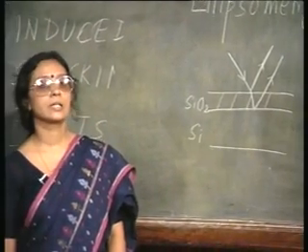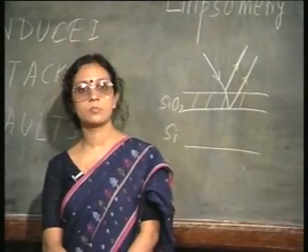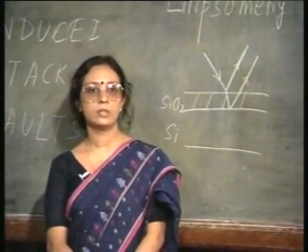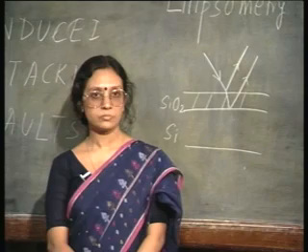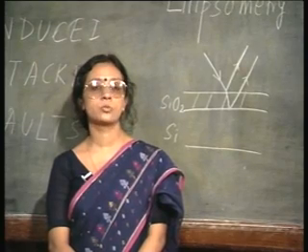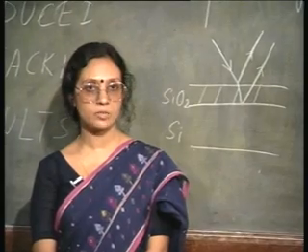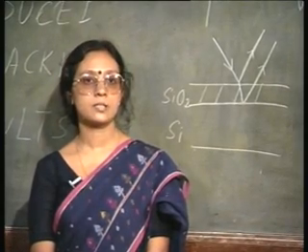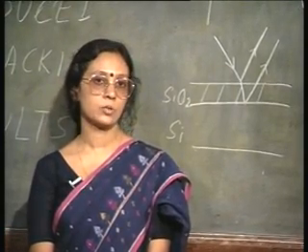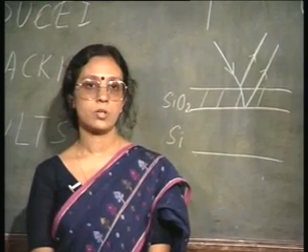There are of course other techniques like the interference fringe method. In that case also, the sample with the oxide film is subjected to monochromatic light, and by observing the interference fringe pattern and measuring the distance between the fringes, one can calculate the oxide thickness.